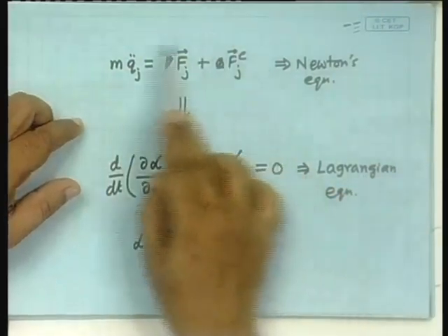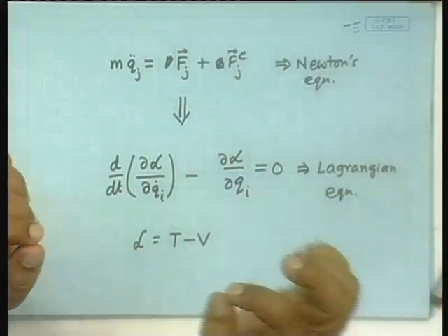In case of the Newtonian equation, what did we do? For every mass point, we identified the forces acting on it, and in order to facilitate that, we drew the free body diagram that you probably learnt in the mechanics class, right. So, we drew the free body diagram, then we either wrote force is equal to mass into acceleration, or if we write in the D'Alembert's way, the free body diagram itself contains the m q double dot. So, just a balance of the forces.